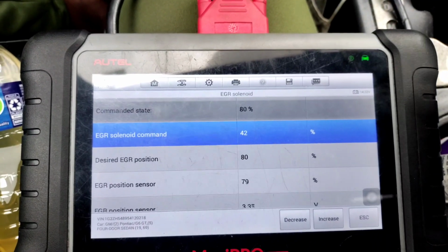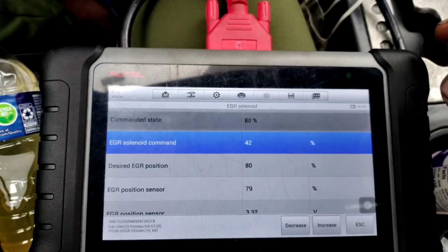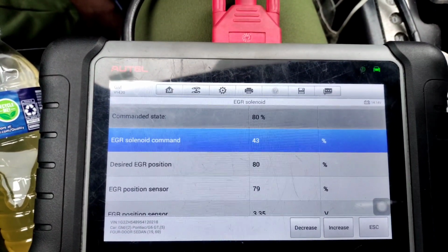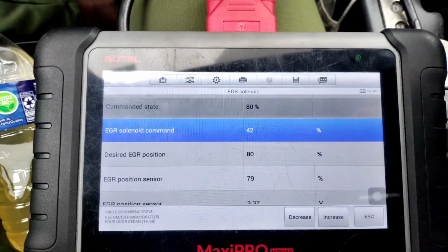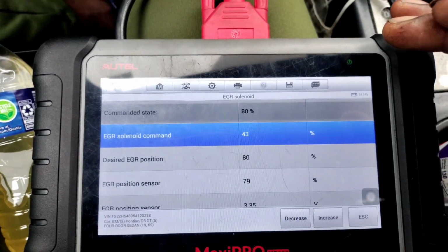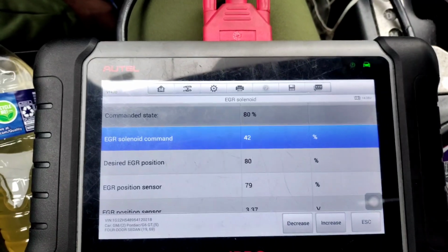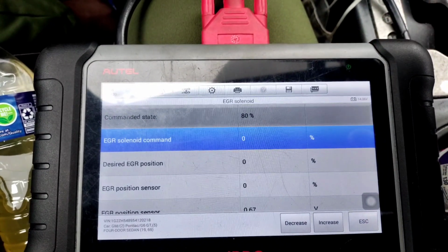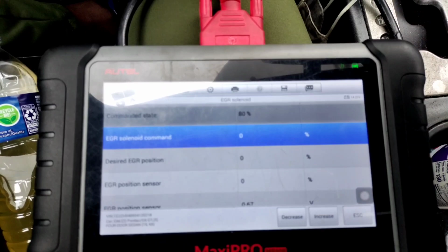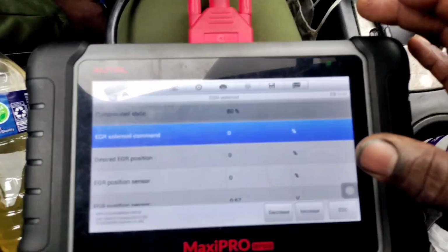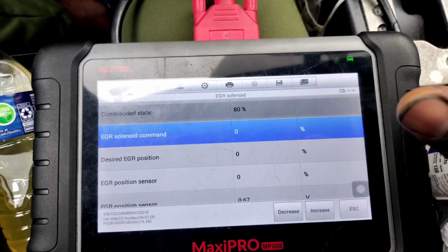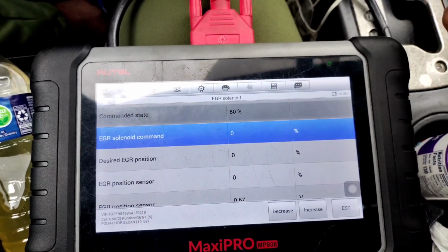but even though we have lift, there's no change in idle, which sounds like there's obstruction, or there's something detached with the plunger, like the valve, or pintle, whatever you want to call it, the valve is not opening, and there's some disconnection between the valve and the lift sensor. I mean, it's a shaft.